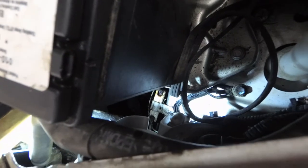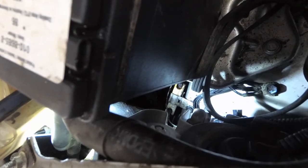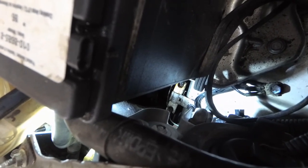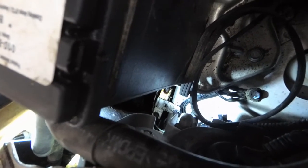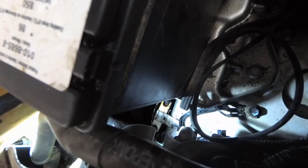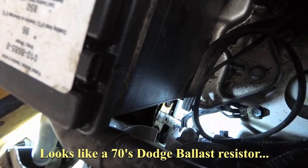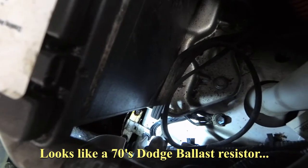Well, somebody got paid to use up a bunch of dropping resistors from the 70s. So there's the dropping resistor attached to the left front frame rail, just in front of and below the battery. I don't know if you're going to be able to see it in this diagram or in this camera angle, but that's right out of circa 70. You know, spade terminals, screws on them. Well, we'll check to see if there's power being sent to that when we command the relay on.